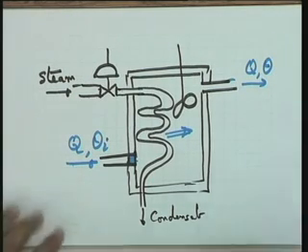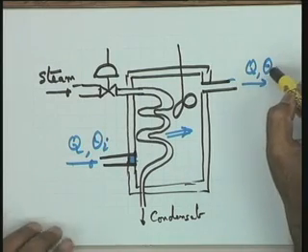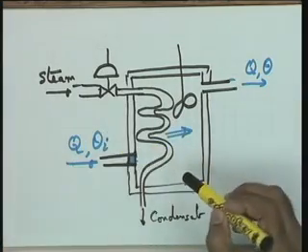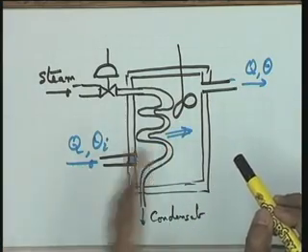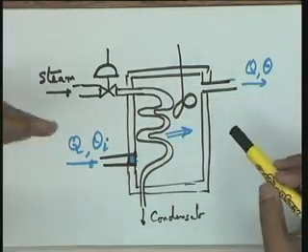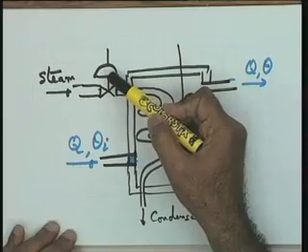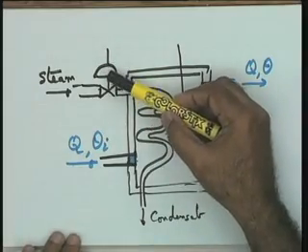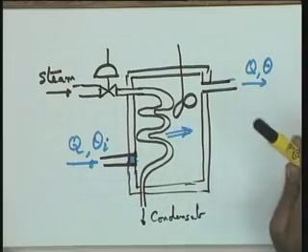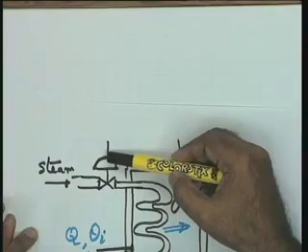So, you should give me the mechanism to set the command value of theta. Theta I, the temperature variation of the inflow liquid, is a disturbance on the system. I want to control this theta, and what is the manipulated variable? The manipulated variable is this control valve position, because controlling this position is going to control the steam and hence the steam flow rate. Come on please, suggest the hardware. I particularly want you to give me the flexibility of using a pneumatic control valve for controlling this position.